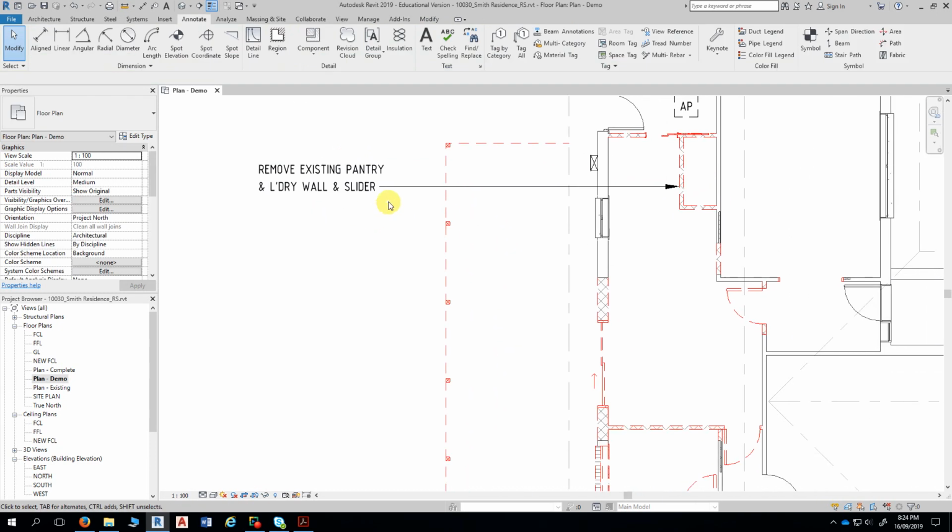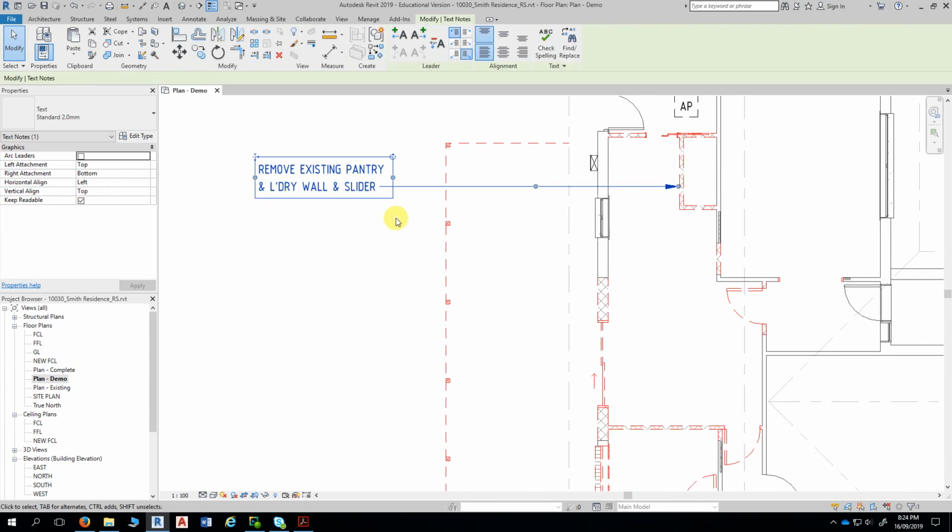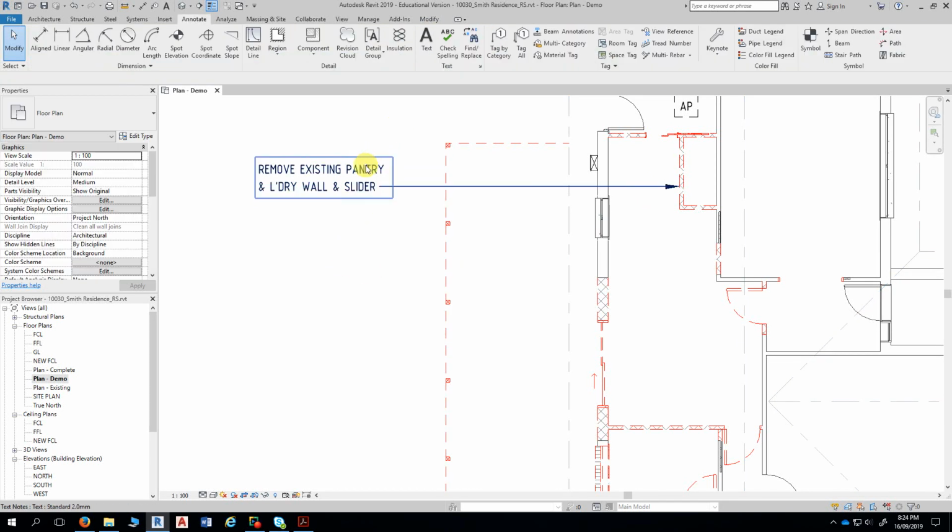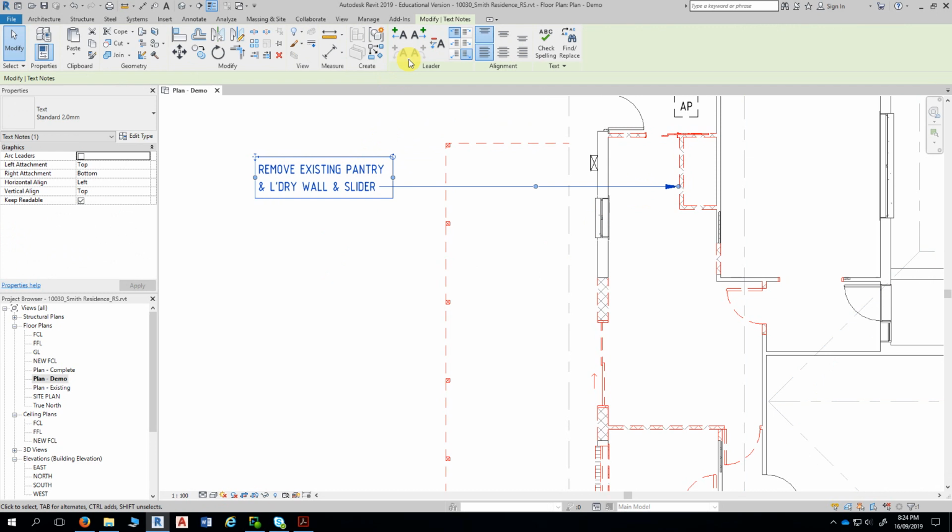Now, with the second note, you are required to include a second arrow. You'll do that by selecting the text itself, and if you go up here, add right side straight leader. If I click that, it adds a second arrow. If I click it again, it adds a third and a fourth and a fifth. If you want to remove those, you can do this: remove, remove, remove.